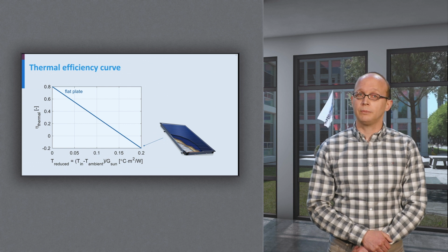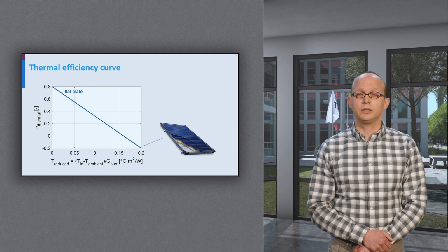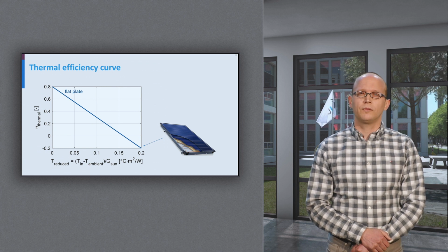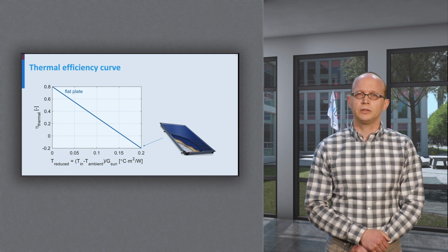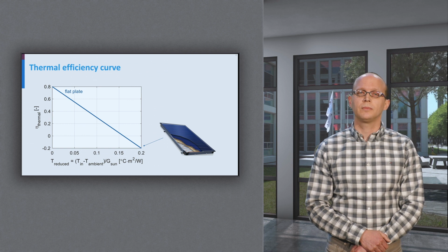With increasing inlet temperature, the thermal losses to the ambient increase, and as a result, the thermal efficiency decreases. For very high inlet temperature, the thermal efficiency drops below 0. At this point, the water flowing in cannot be heated any further.